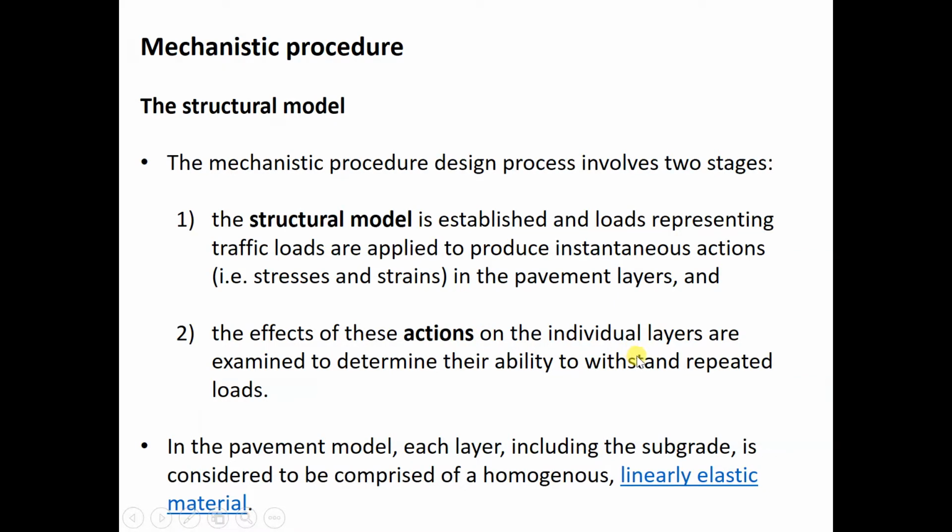It could be the wearing course, and then you have the base course and subbase, and one of these could be cemented. Cemented means that it's a bound layer of cemented materials. So we need to see what the responses are, and also the subgrade as well. There'll be various responses to the traffic loading.